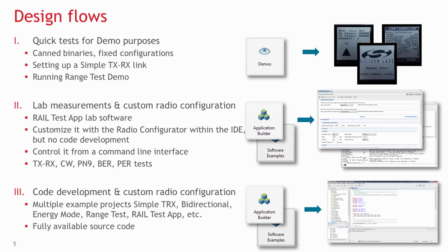There are three main design flows that you can follow when developing with the EFR32. Number 1, quick tests for demo purposes. There is no interaction with any IDE or radio configurator. You can just download pre-configured binaries to set up a simple TX-RX link or a range test.